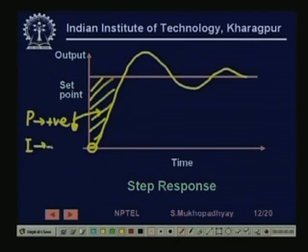So it is positive and going up, right? At this point error is 0. So the proportional controller output is 0, but because the integral controller output is still positive, the plant continues on this path, right?